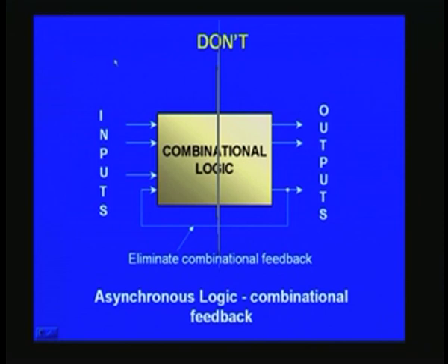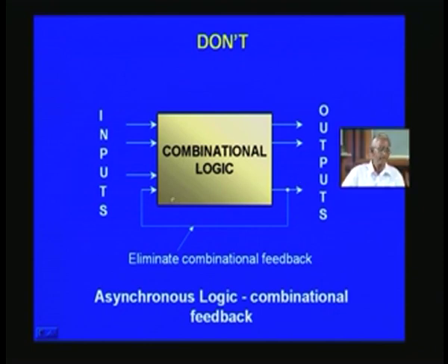And the common mistake that we made is to take a combinational output and feed it back, and this is detrimental in making a chip as such, because for example, if you apply a 0 at the input here, the combinational logic might produce a 1 here, and then the 1 being fed back, it keeps on rapidly switching from one state to another, and this will be uncontrollable as such, and thereby it will not work in the ultimate chip that you have designed. And furthermore, this may be rejected at the synthesis level itself.